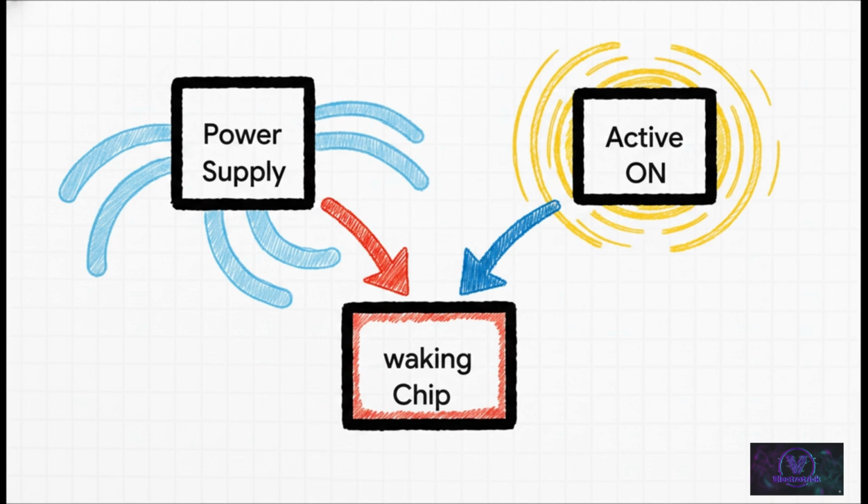Your active, humming along logic has stored charge, right? When that sleepy 0-volt domain wakes up next door, physics dictates that charge flows from the higher potential active logic down to the lower potential off domain. So your waking block is literally stealing charge from your working blocks.